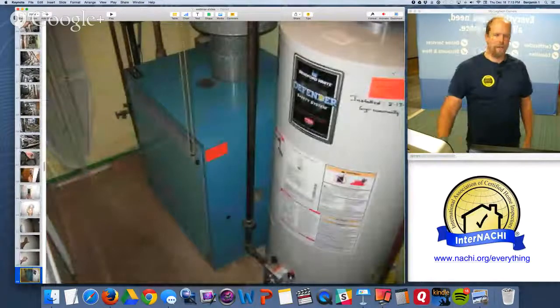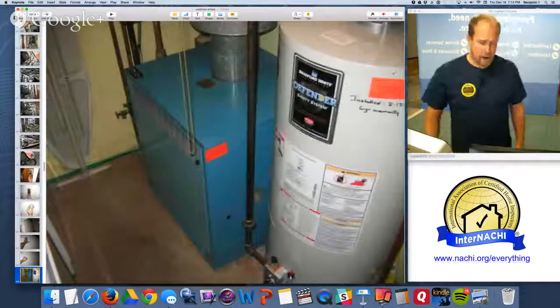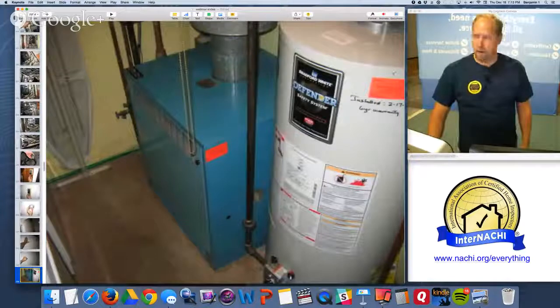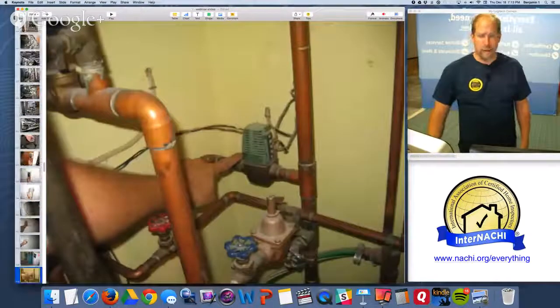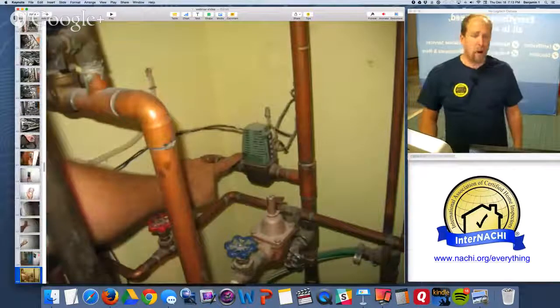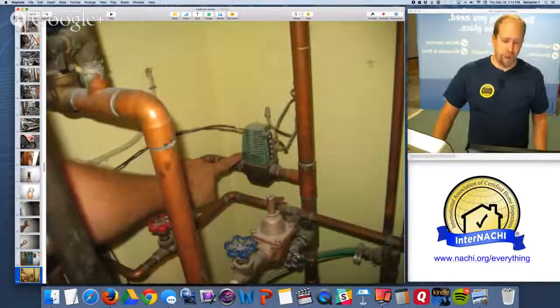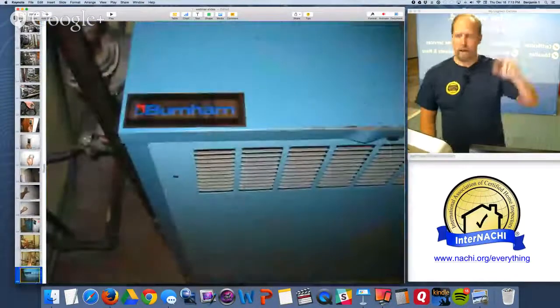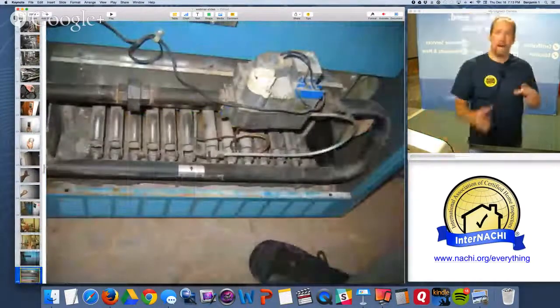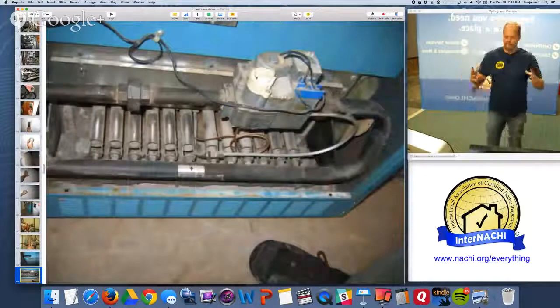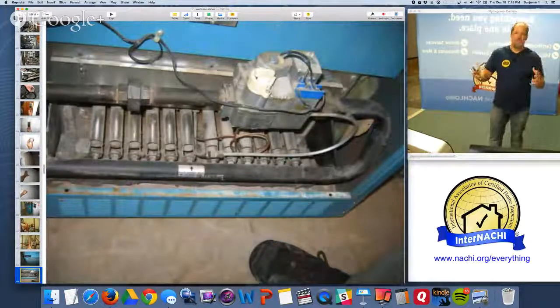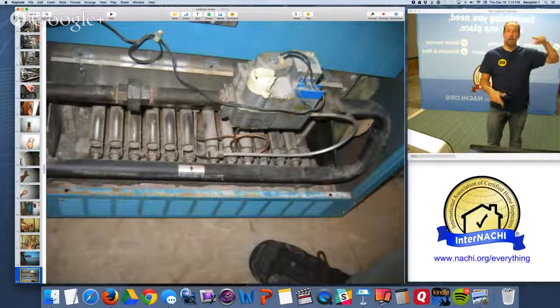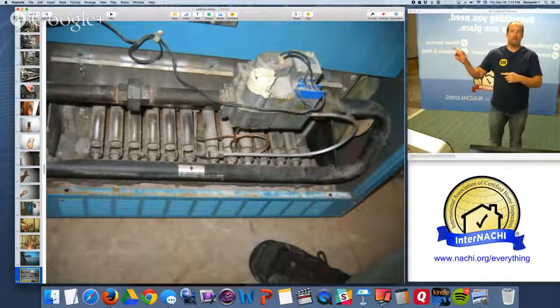There's a boiler system right next to a hot water source, gas-fired boiler, gas-fired hot water tank, natural draft at the boiler, natural draft at the hot water tank. The components of a boiler system are a bit complex. There are valves controlled by thermostats that allow the water to flow because there's a pump. A boiler is a big container, typically cast iron, filled with water, flames underneath, heats up the water. A pump turns on at a certain temperature and circulates the water throughout the house.